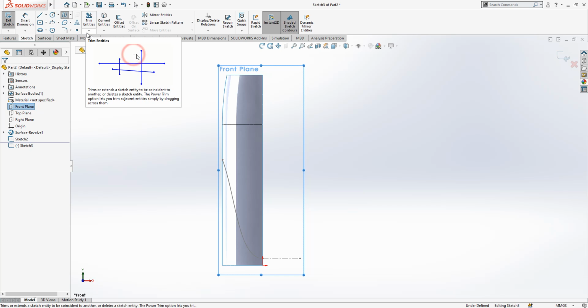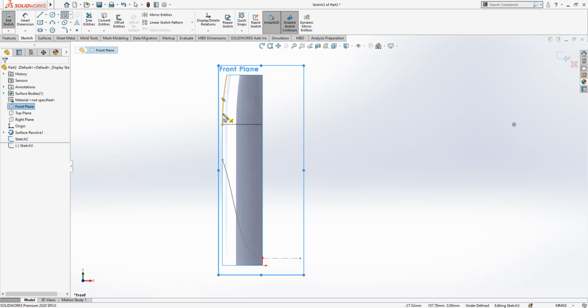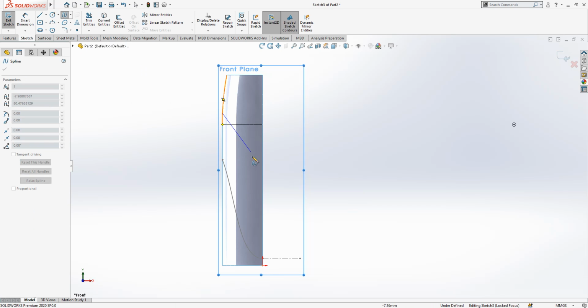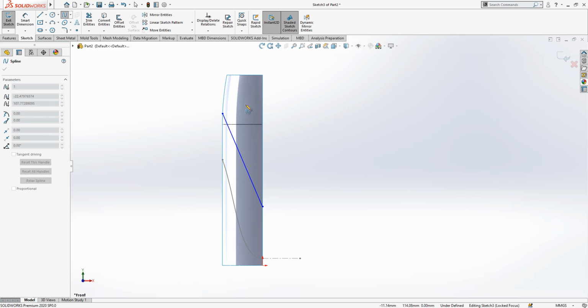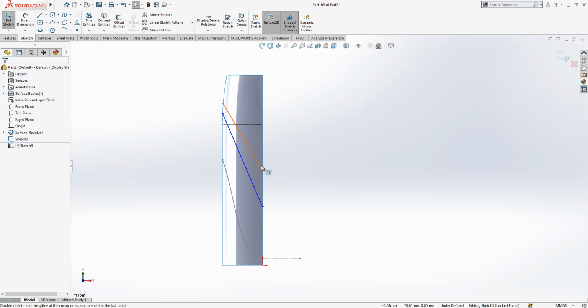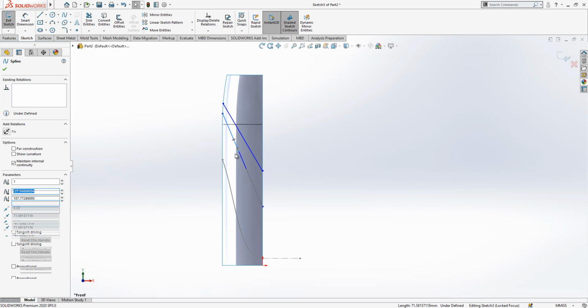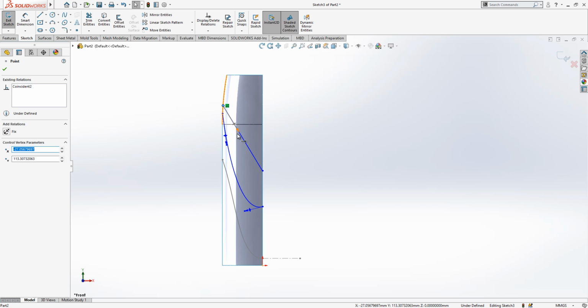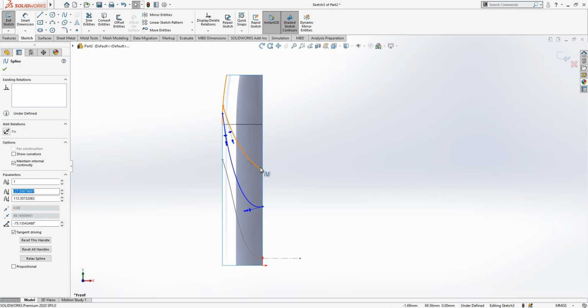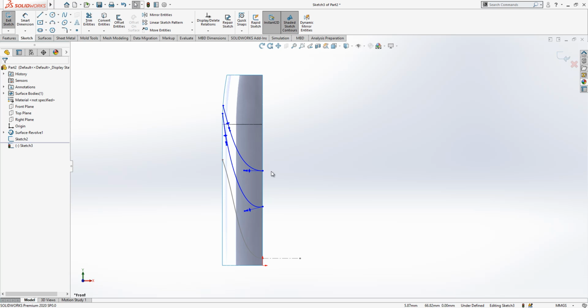Now I will create 2-time spline. If I'm right, they were starting from here. One comes like this, another like this, and don't do like that. It is a mistake because this is a midpoint, and then you cannot control your spline anymore. Good, because a midpoint will not allow you to freely travel as I do now. So I little bit move them, and then I will start to give some dimensions.